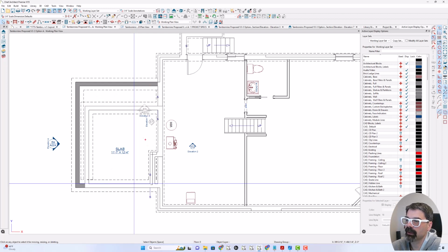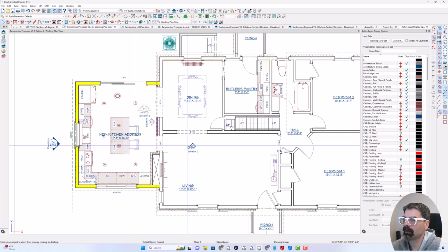In addition, this slab is going to remain where it's at. We're going to add a slab out here that's flush with this slab, which is -3 inches from the living room space above. But we want the addition to be flush across here, makes sense.